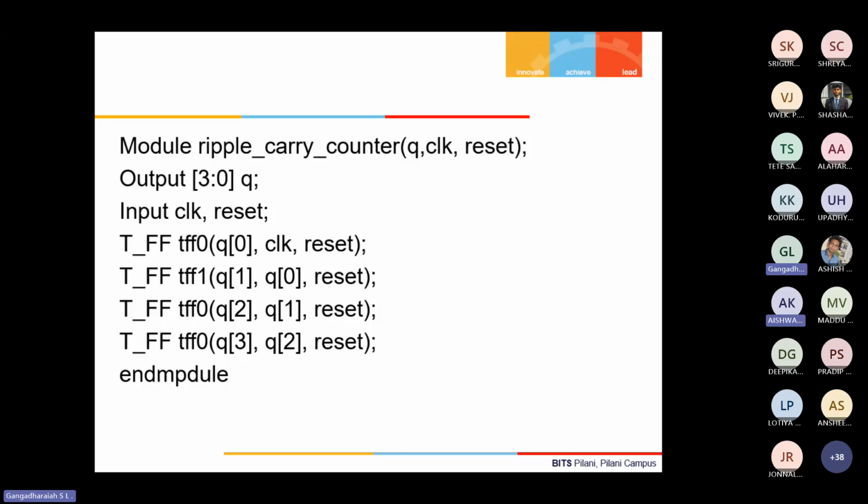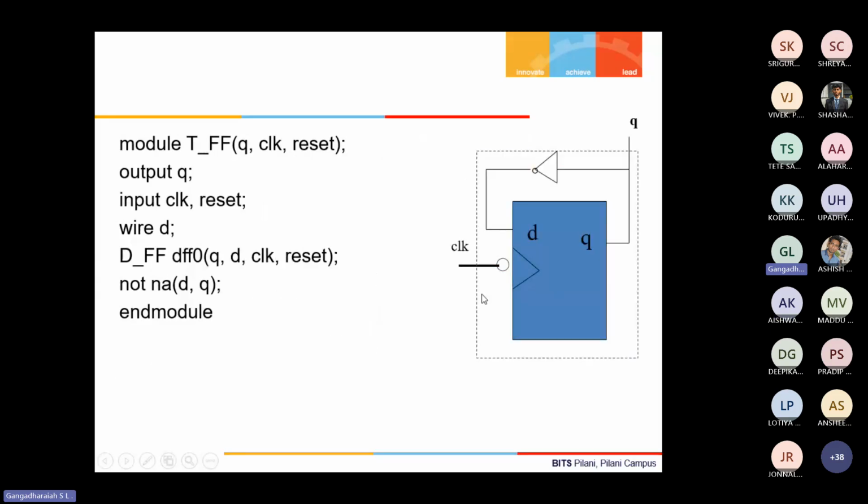Output Q is a wire. Even if you write it as output wire Q, no problem. It reads it properly. And all inputs are wires by default. That is why probably you are not explicitly declaring it, but they are wires by default. No doubt it is supported. And as you said, in the verification environment also it is supported. Okay, thank you, sir. Bye.